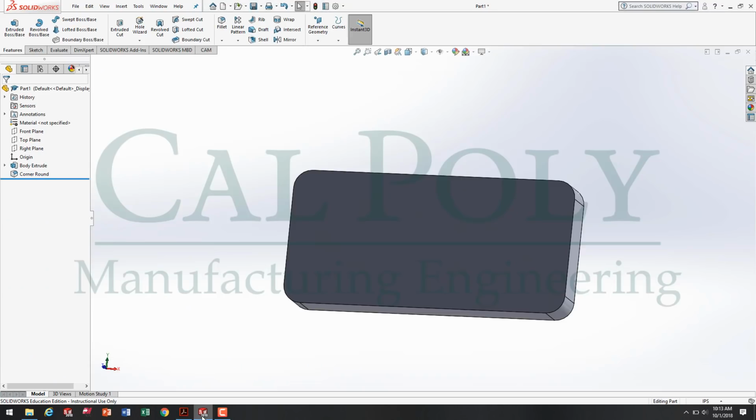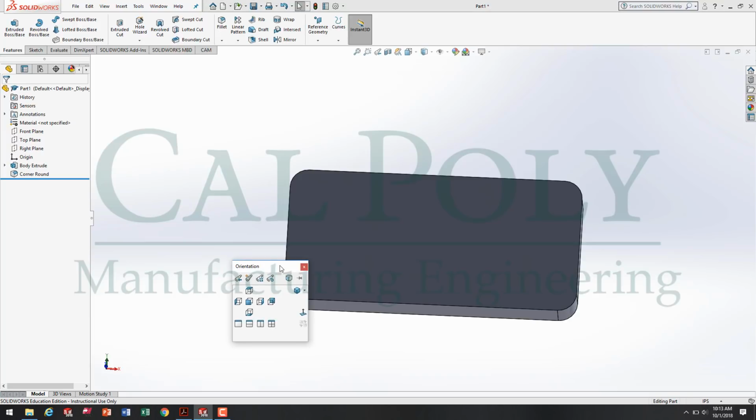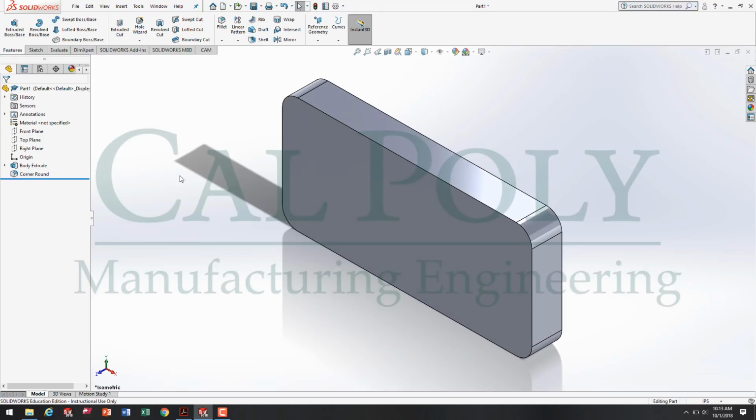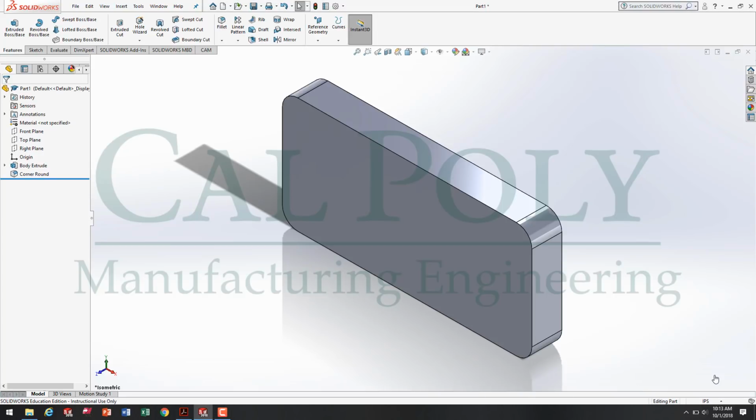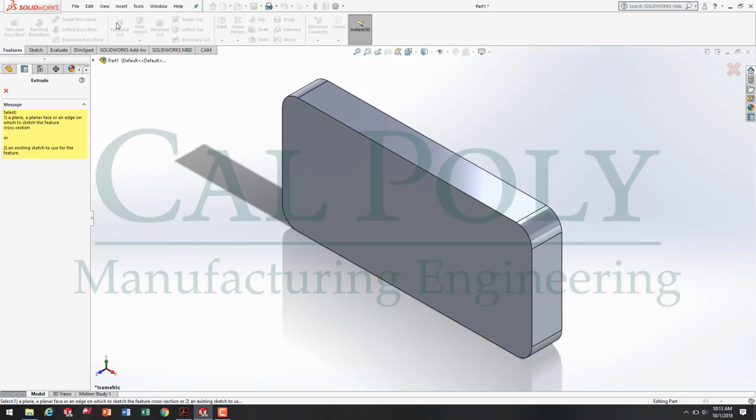So moving back to SolidWorks, looking at the model, remember we can always hit spacebar to bring up the orientation toolbar, and then isometric to orient ourselves with our model. In order to create a cutout on the front face, we're going to use our features tool, the extruded cut. So I click on extruded cut.